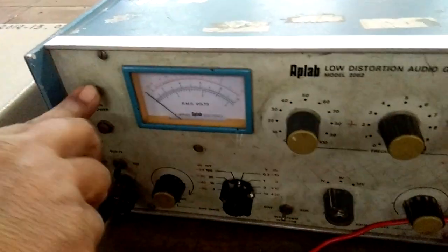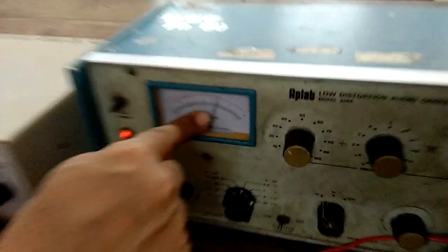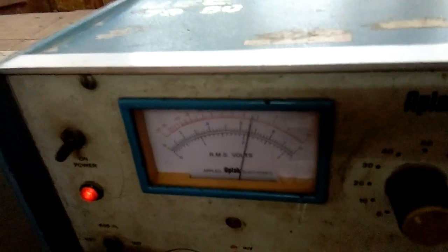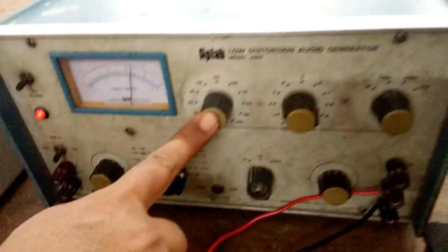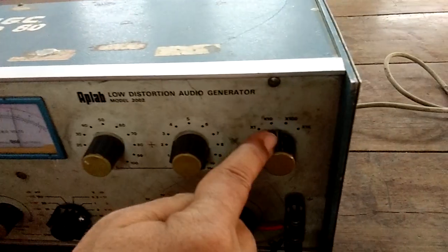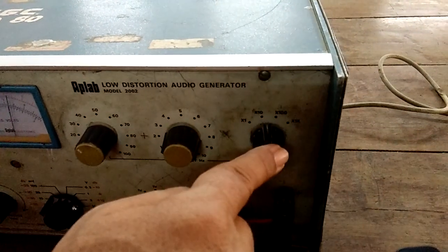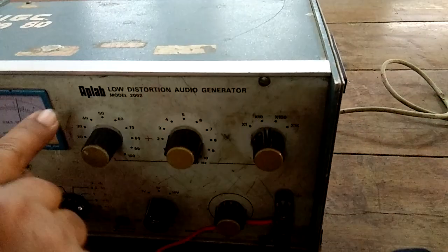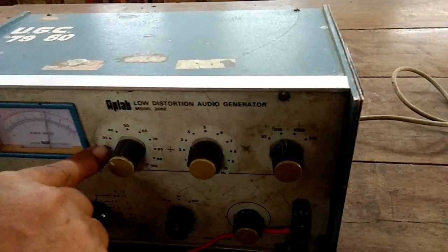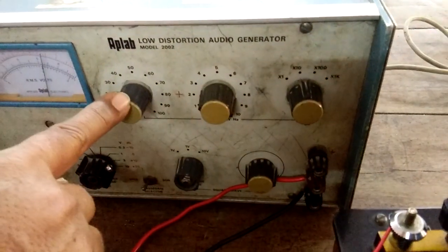First, set the input voltage from this generator. From the generator, 20 millivolt is adjusted by using this knob. Select the frequency from this knob. This frequency is this knob multiplied by this selector. So if it is 20 and this is on 100, it is 20 into 100. If it is on 10, then 20 into 10 is 200 Hertz. So you can change this frequency with the help of this knob and this knob.